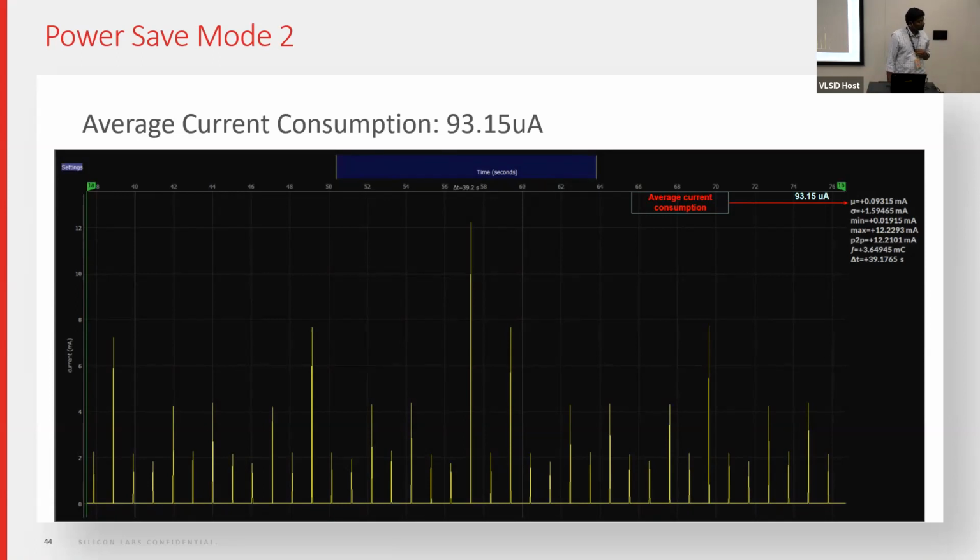If the device is unable to wake up at the particular time, that data is lost, and the station has to wake up for the next DTIM beacon. Suppose it has to wait for three or four beacons because it is unable to get it.